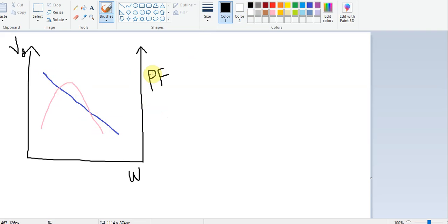Now I'll come to the field. I'll take my proctor needle. That proctor needle is plunged into the compacted soil layer, and it will give us some resistance force. Now I'll refer to my calibration curve, and let's say this is the resistance force given by the proctor needle for the soil compacted in the field.